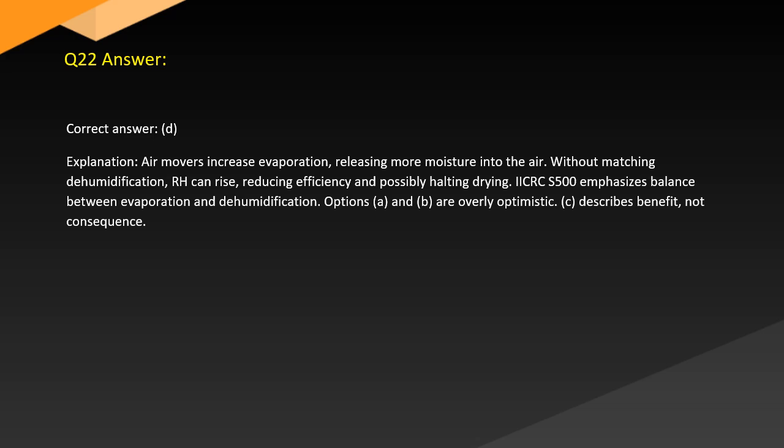Answer. Correct answer, D. Explanation. Air movers increase evaporation, releasing more moisture into the air. Without matching dehumidification, RH can rise, reducing efficiency and possibly halting drying. HRConquer emphasizes balance between evaporation and dehumidification. Options A and B are overly optimistic. C describes benefit, not consequence.